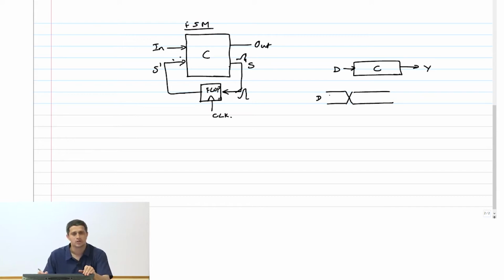So this is a timing diagram that you should get used to. This transition means data is switching from one state to another state, but both are deterministic. We know what they are. So this will be data D1, this will be data D2. And the reason I am not drawing it as a binary function is this could be a bus. This also could be a bus. So any change in any of the inputs is what we are capturing through this transition here.